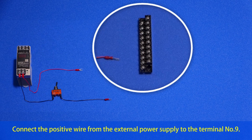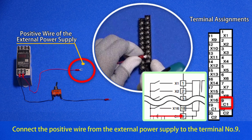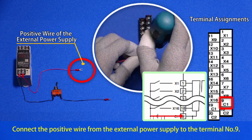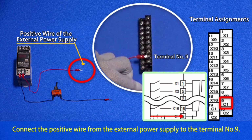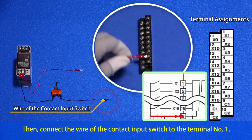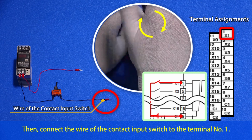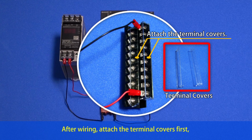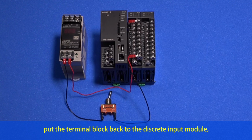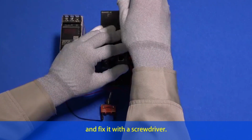Connect the positive wire from the external power supply to the terminal number 9. Then, connect the wire of the contact input switch to the terminal number 1. After wiring, attach the terminal covers first, put the terminal block back to the discrete input module, and fix it with a screwdriver.